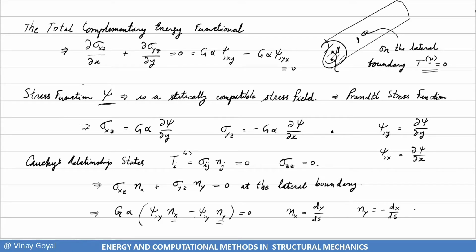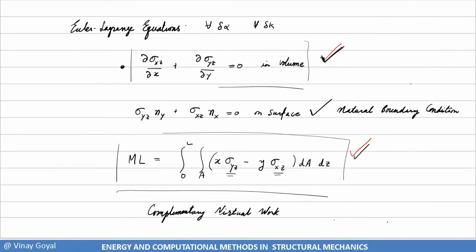And what I'm going to approximate then is the displacement field. So again, in the total potential energy, when you're using that and you minimize pi, the essential boundary conditions there are the kinematic boundary conditions, and the natural boundary conditions are the stress conditions. And the Euler Lagrange equation will be some sort of stress equation like you see here.